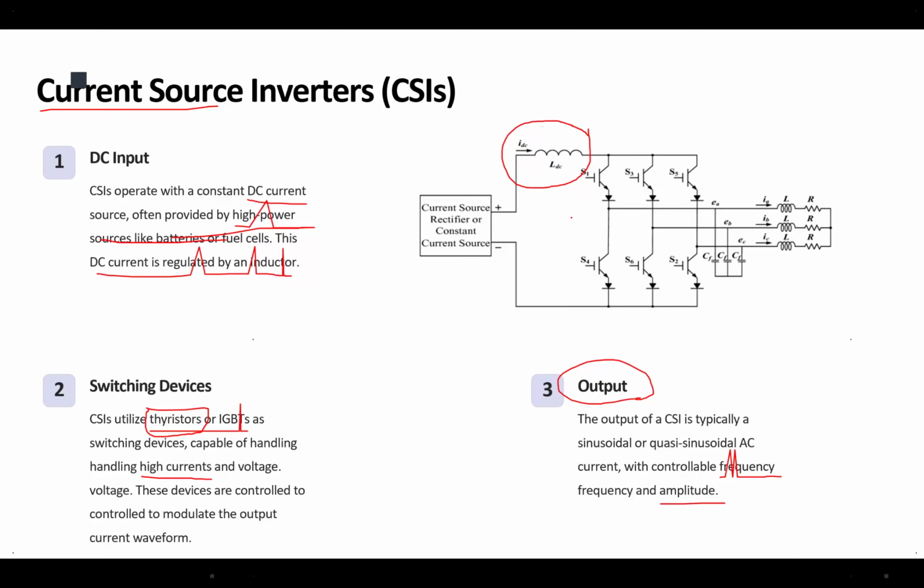But for the turn-off, simply cutting off the gate would not be enough. You have to have another control circuit in parallel with your switches to force them to cut off the current by applying the reverse voltage. Did I answer your question?